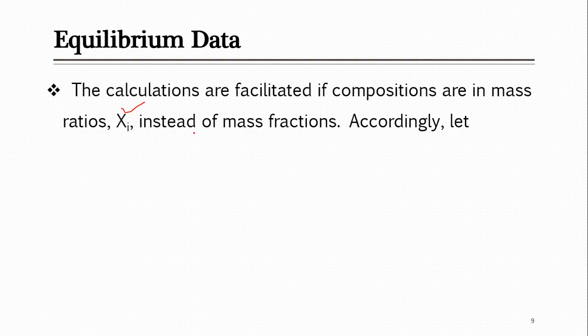So our results or equations are more convenient to use if we use this capital X instead of small x, which was the mass fraction. But also if you recall, there we discussed some relationship between this mass fraction and this X capital mass ratio. Just look at those equations in the absorption section. But here you don't need those, we are just going to use this mass ratio equation.